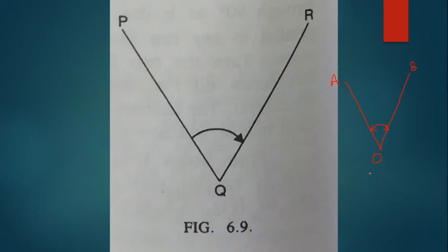So here in the initial stage, our telescope is directed to some other direction, and with this position we got vernier A0 exactly matching with the main scale 0. We do not want to disturb the angle, but rotate the telescope such that it will be exactly in line with OA. So for this we can release the lower clamp. Am I clear up to here? I think I am clear up to here.